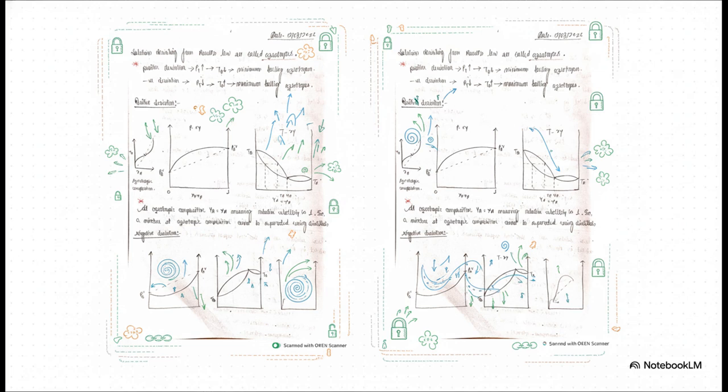And you can actually see these weird behaviors. Some mixtures are more eager to turn into a vapor than Raoult's law says they should be. We call that a positive deviation. Others are less eager, creating a lower pressure. That's a negative deviation. But either way, they can create that one sticky point, that azeotrope, where the whole separation process just grinds to a halt.